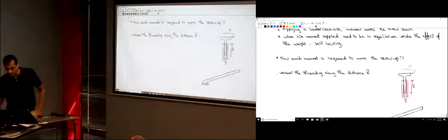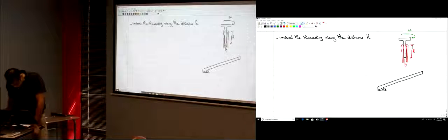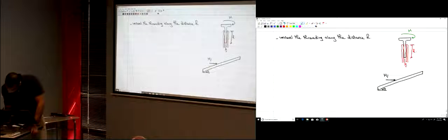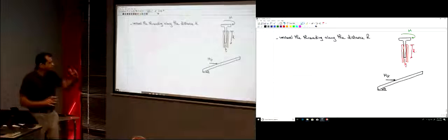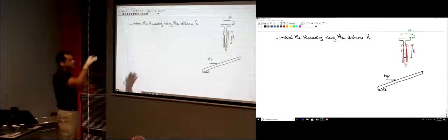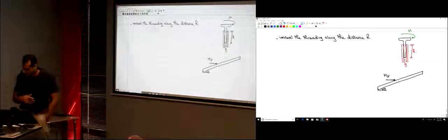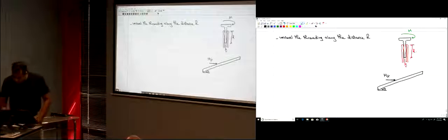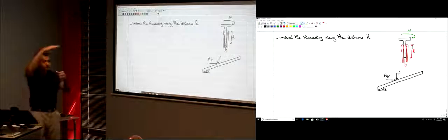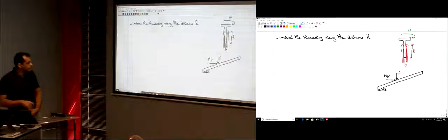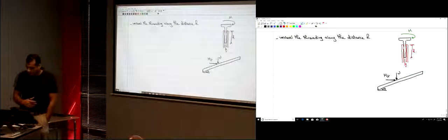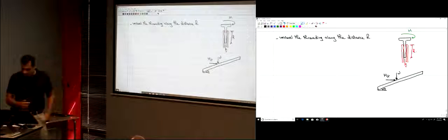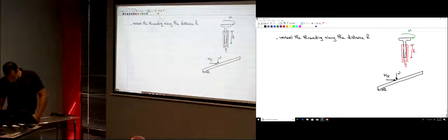So now I have this horizontal force, M divided by R, that wants to move this thread up along this distance H. Also we have the weight of the screw itself, or any vertical force applied on the screw, plus its weight, W. Now this wants to move up, so here we have the direction of impending motion, it's in this direction.